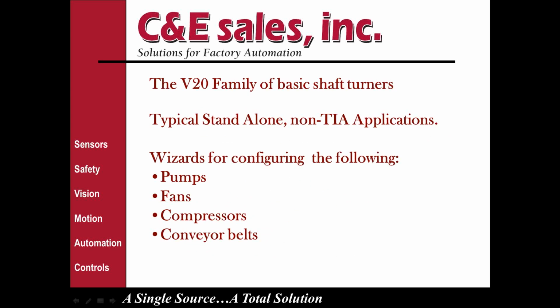It's intended for individual pumps, fans and compressors, which are its big use. Also, there is a wizard for conveyor belts so that you can stage the ramping up and ramping down of the speed control. In pumps and fans, it will do variable torque, so it will optimize the output to the motor to meet the pump curves or the fan curves. You can also do some staging of pumps with the drive for balancing of loads.